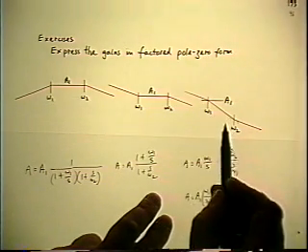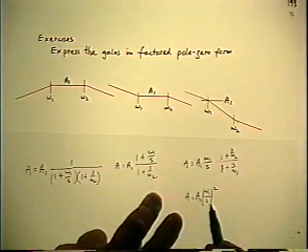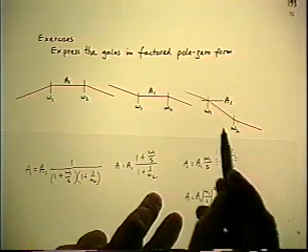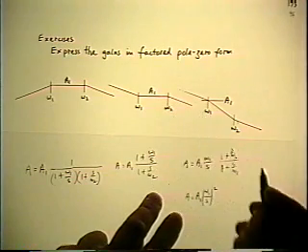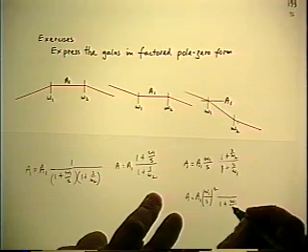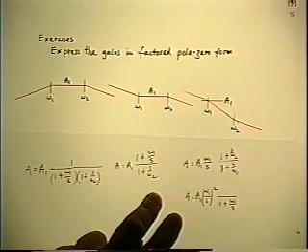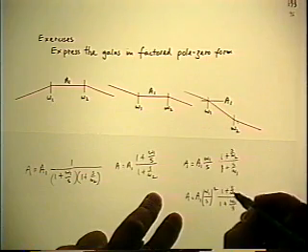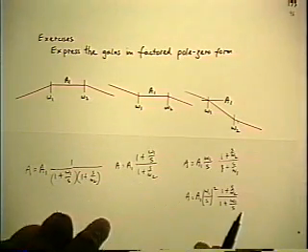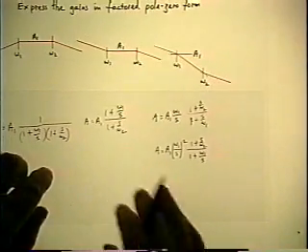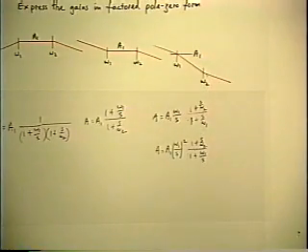Now, the middle asymptote has been adopted as reference, so now you look both down and up and see what happens. And when you look down, you see a concave downwards corner, which is a pole, but it's an inverted pole at omega 1. And when you look up, you see again a normal zero at omega 2. So now we have two versions. Of course, they have to be the same.